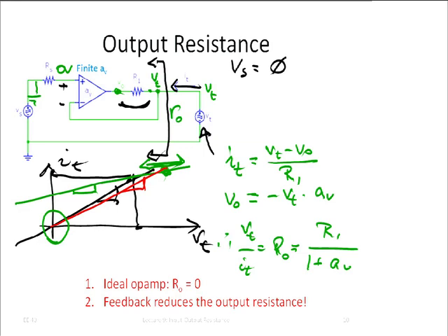And that's also, for example, what is inside the lab power supply that you use. The circuits inside have an absolutely finite output resistance of probably an ohm or so, maybe a little bit less. And then they apply a lot of feedback with high gain to make it less than a milliohm. Okay? It's a very wonderful thing. We do that all the time. Turns out it's very, very difficult. Ultimately, all these circuits are made out of transistors. Well, the output resistance of transistors is not that small at all. Okay?